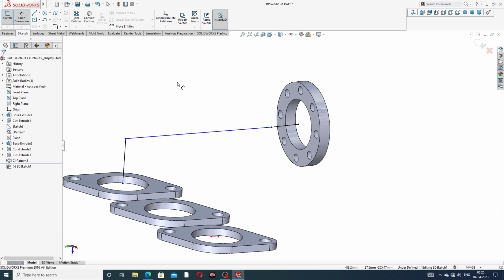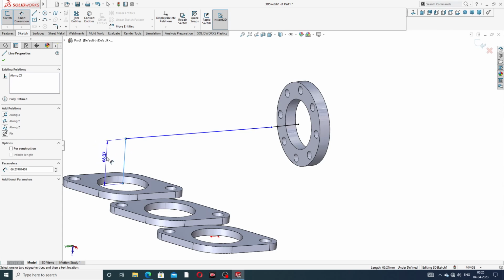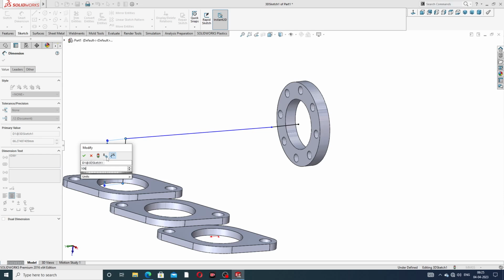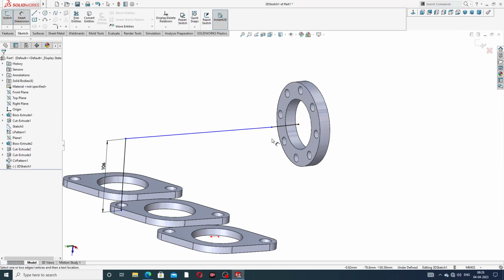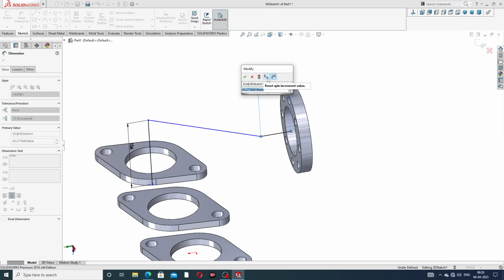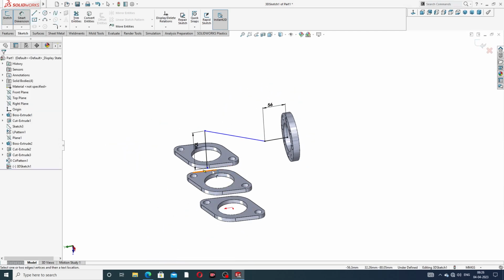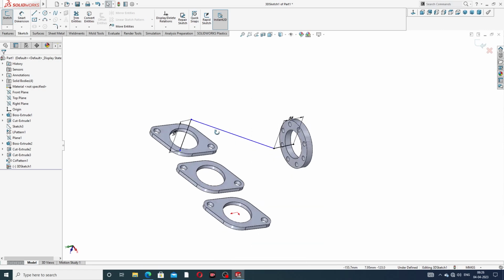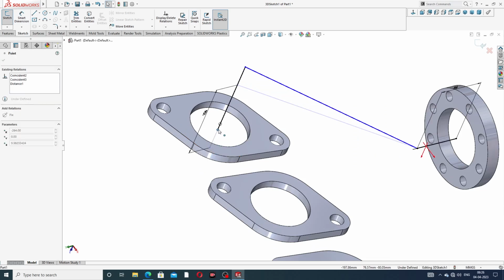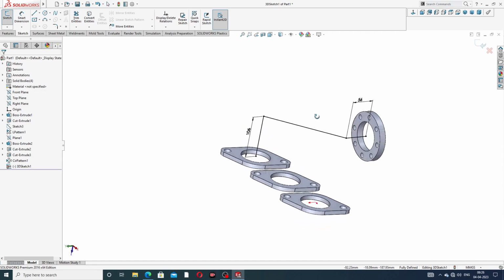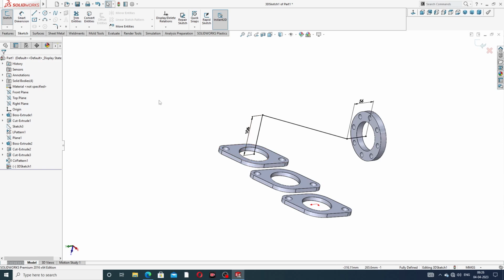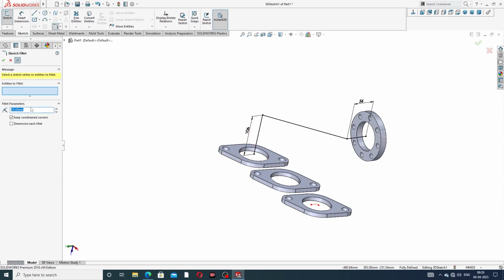And again align a dimension. This dimension is 106 millimeter, okay, and this diameter is 56 millimeter, okay, but some point is dragged to the below side, and connect to this point, okay, and use a very important fillet, this one uses 68 millimeter, and this uses this, and okay, and again select 98 millimeter and this uses this, okay,